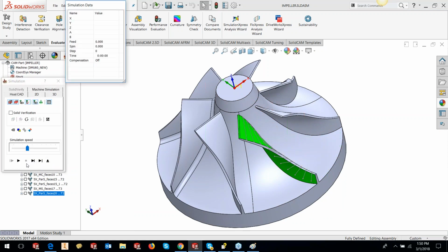I have created a very nice looking bottom tool path. You can see that it does a neat path and it'll make sure that it doesn't collide because we already have checked for the collision between these two blades when we created the single pass, right?